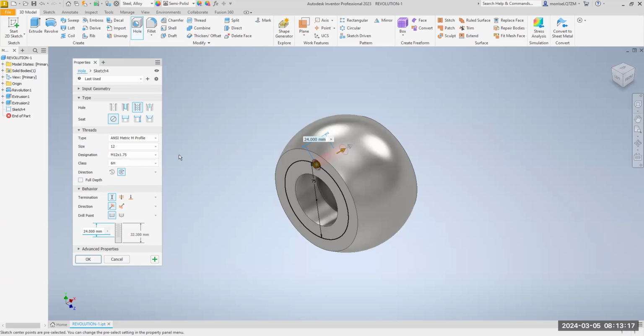And the 1.75 is called the pitch, which means it's the distance from one thread to the next. It's the space between the threads. Okay? Is called the pitch. Now we want to go through all here. Come down to where it says turn. We want to go all the way through this part. Now, say full depth. You want the thread to be full depth.